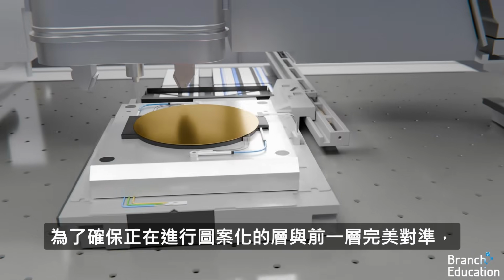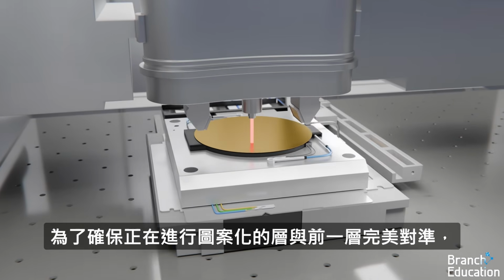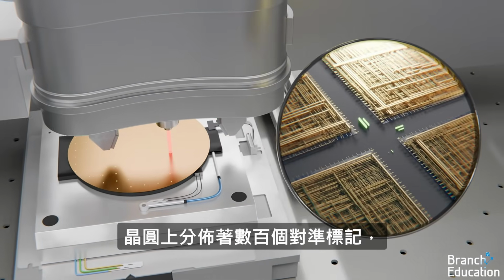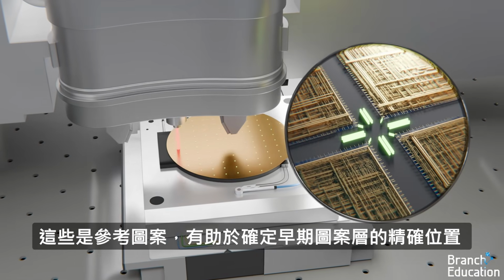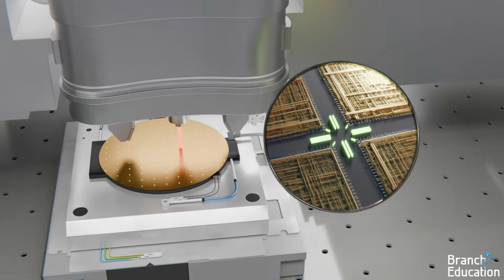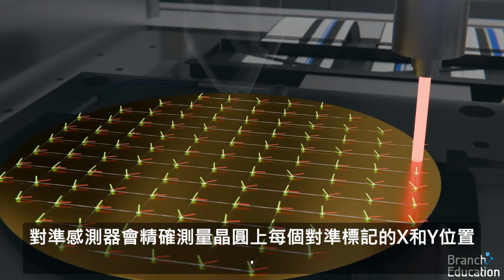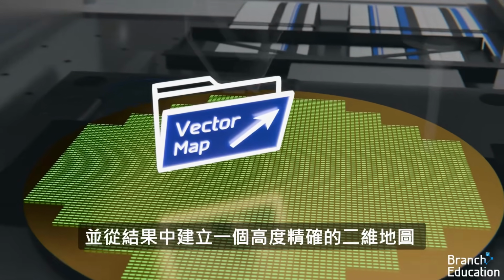To make sure that the layer being patterned is perfectly aligned with the previous layer, the entire wafer is thoroughly measured by the alignment sensor. On the wafer are hundreds of alignment marks, which are reference patterns that assist in determining the exact position of the earlier layers of patterns. The alignment sensor meticulously measures the X and Y positions of every alignment mark on the wafer and builds a highly accurate 2D map from the results.